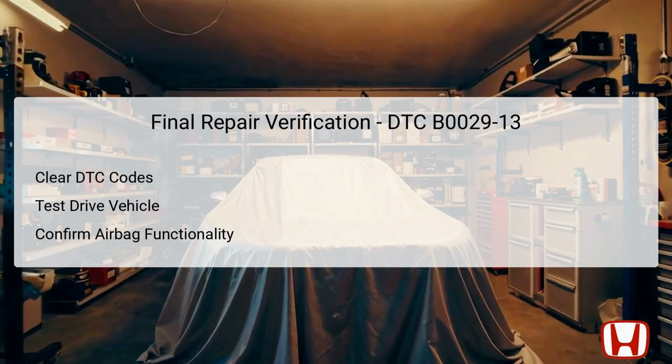Additionally, if possible, perform a system self-check to ensure all airbags, including the curtain airbags, are operational under correct trigger conditions. This step allows verification that all repairs were successful and guarantees safety upon vehicle operation.